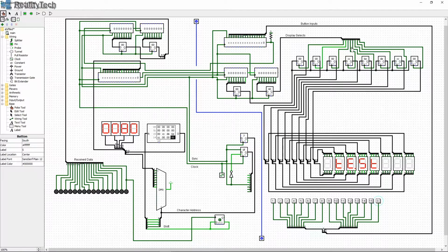Now what you would normally do is these would drive transistors, and these would drive either the common cathode or common anode on the display, with the drive for the segments coming from here. As you can see, something very similar is happening, but we're having to latch the segment data into here. This is because the provided 7 segments here don't provide any method of latching the data in.